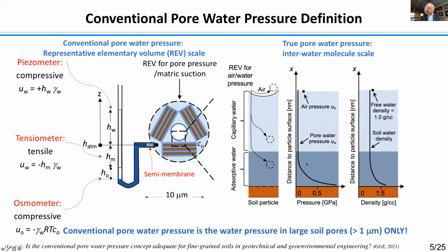How close it is depends on how strong your soil absorption ability is, what I call soil softening potential. Somewhere between 10 to 100 water molecules. But that is very important. You may say, okay, 10 water molecules, it's only 3 nanometers, and our pores are much bigger, as I showed, at least greater than a micrometer. But remember that the clay we have could have a few hundred square meters per gram. So that makes a huge, tremendous difference.